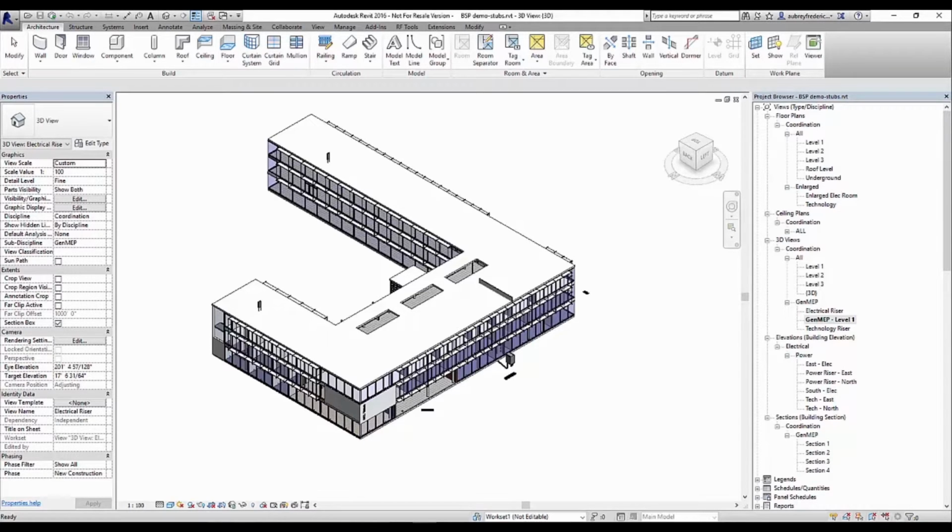So my thinking here is, during that downtime before we start modeling, there's a lot of information that's provided as far as layout, feeder schedules, and sizes of equipment. We can take that information, and for some of us that do project setup in Revit, we normally use a template before we get started.